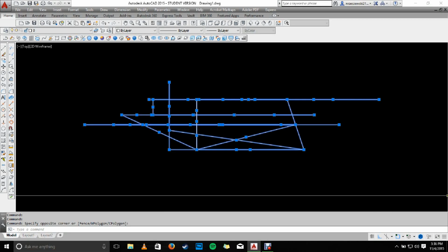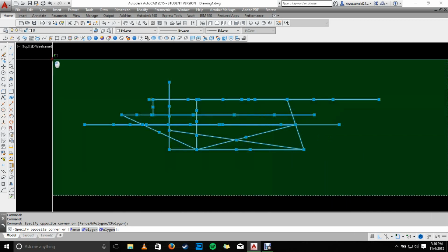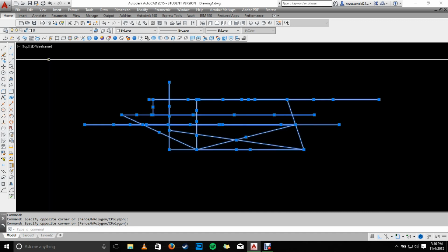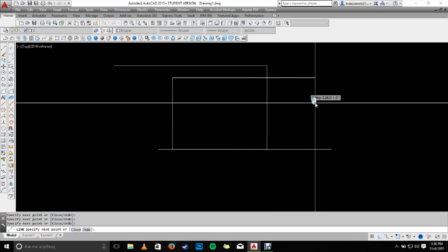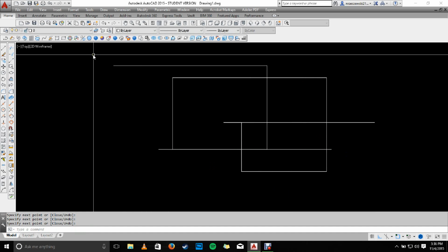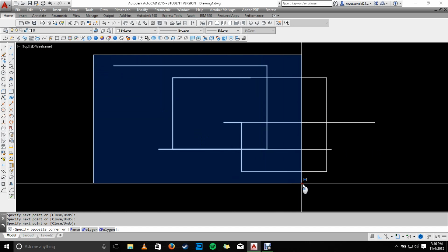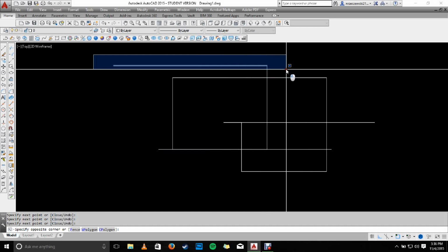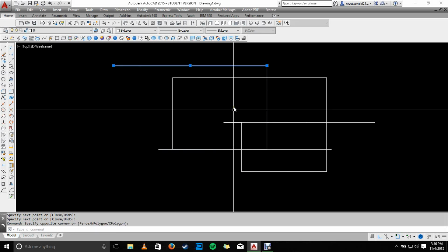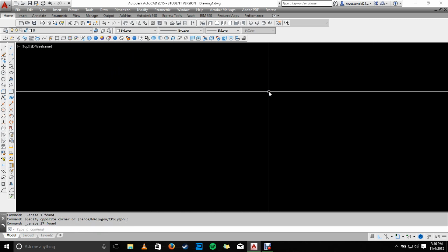But what we're going to do is just take this and drag it this way, because when you drag the green, it selects everything it touches. So when you do that, it highlights everything, and then just simply hit delete. But let's just say, for example, you did it the other way. I'm going to draw a couple of these lines just so you can see it. When you drag this way, you're going to get blue. And as you see on the screen, blue only highlights what it has completely inside of it. So if you only have that one line inside of it, it's only going to highlight that one line, and you're only going to be able to delete that one line. So I recommend just using the green most of the time because it hits everything that you need to get.